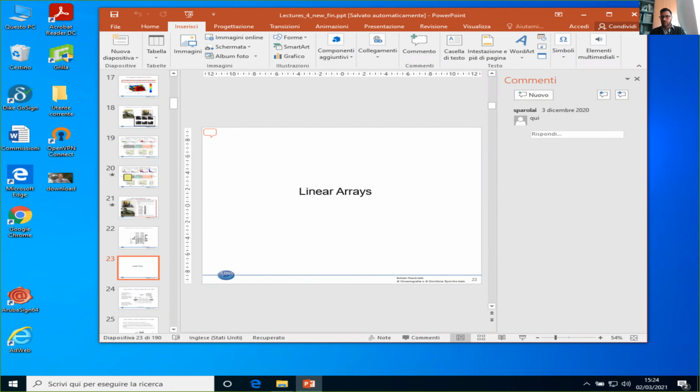But as I said, even to start with simulation, you have to have a good knowledge of the starting parameters, like stiffness or other parameters, so damping of the structure. And very often, only looking at the design of the structure, the model is not really adequate. At least in my experience in the past of working a lot with engineers, every time we tried to make a numerical simulation of a building, starting from the design of the structure and then comparing the numerical simulation, also for small motion, with the observation, we observed nearly always discrepancies.